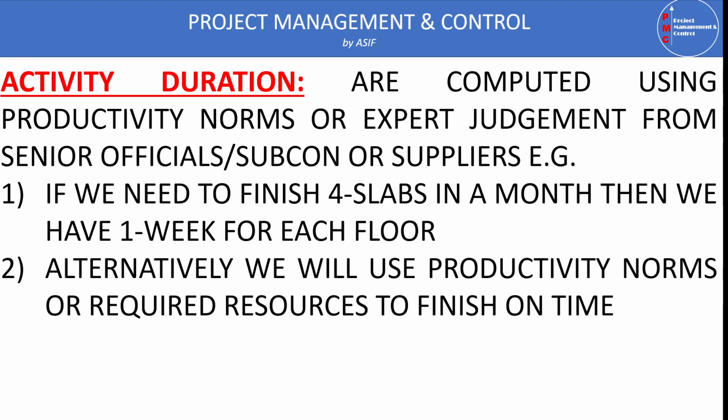But when we are talking about concrete work, it has steel reinforcement and formwork fixing. These take some days, 2 days, 3 days, 4 days, depending on the volume of the work. So in this case, if you divide the concrete activity into further activities, it can be manageable in the program. When we are computing the activity duration, we are using the productivity norms. So what are the productivity norms? Productivity norms are the usual production capacity of our crew, of our labor.